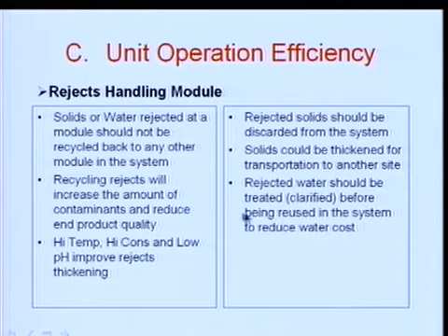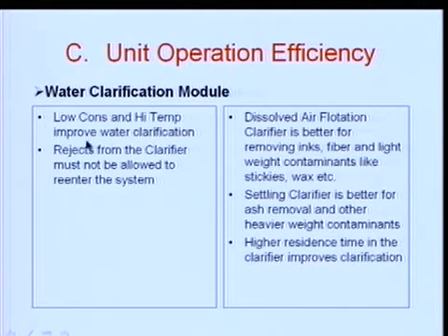Rejected water should be treated, clarified before being reused in the system. Again, I'll talk about that a little bit, but any rejects water should not be recycled back in the system because it will have contamination in it. And water clarification is a very, very important module, either you do it on a washing stage or you do it on a rejects handling stage.